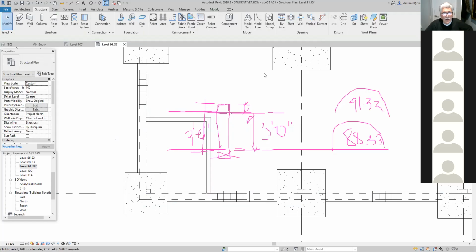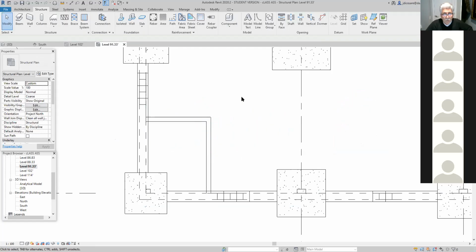And I'm going to clear my drawing. And there's the wall. Okay? Now, to make sure I did it correctly, I always go and double check with the distances here. I say, what's the distance from my wall here to here? Well, 12 feet, that's exactly what I want. I always double check, because after that, if I do anything else with respect to this one, this is 10 feet, perfect.